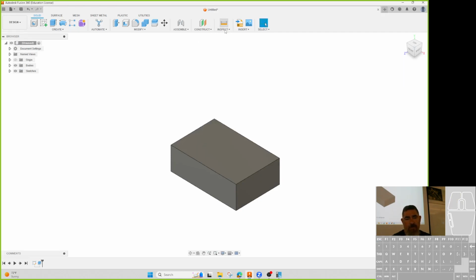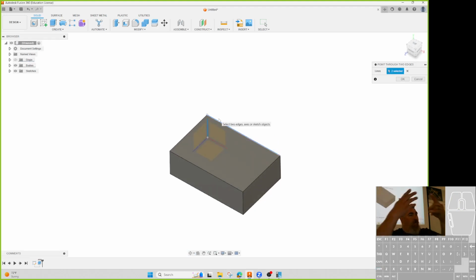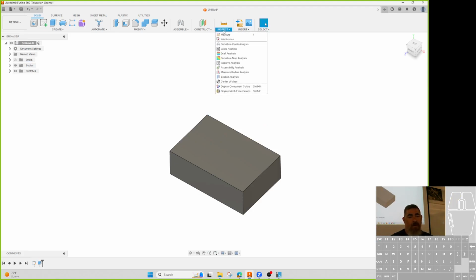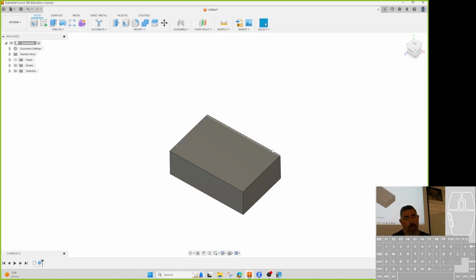and it's not going to let me use the, so I could do even that plane and that edge, and where those things intersect, it's going to give me a point. It's not one I use too often. Point through 3 planes, we can use that sometimes, and sometimes these will be used in combination. So if I wanted to find a point that's on this edge, like an inch from here, that's when I want to use the combination.